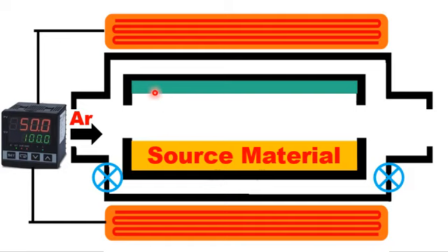They act as transportation gases in a closed space sublimation apparatus. Now, dear student, please note that the interesting fact to notice here is that the distance between the source material and the substrate used in a closed space sublimation apparatus is around 1 to 3 millimeters. So they are at a very small distance from each other. This is not common in other physical vapor deposition techniques.